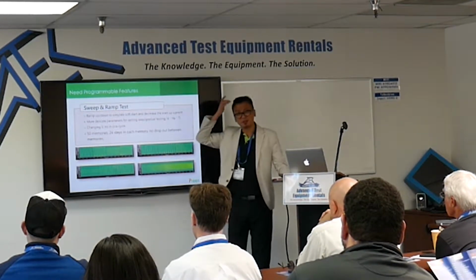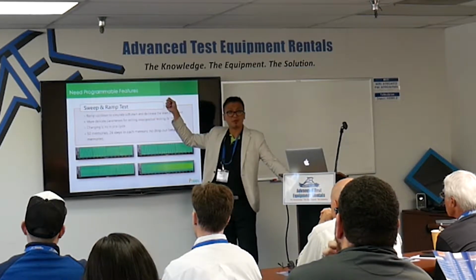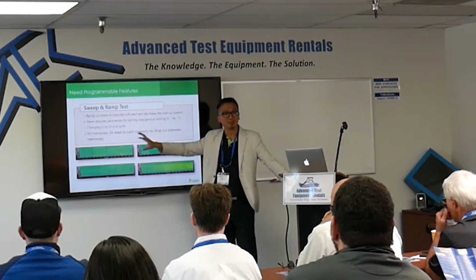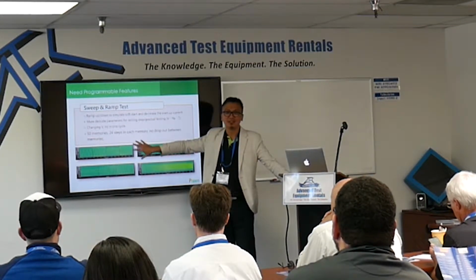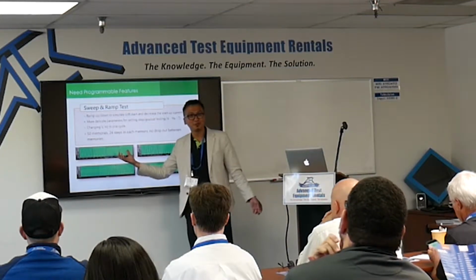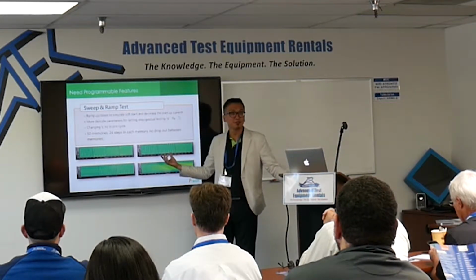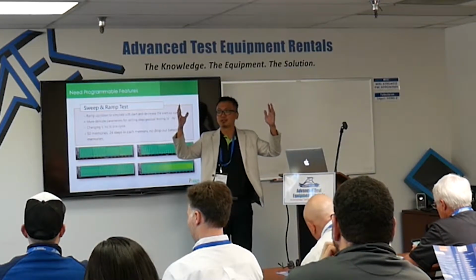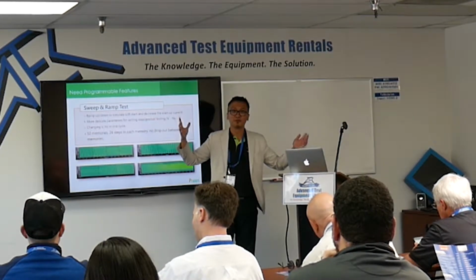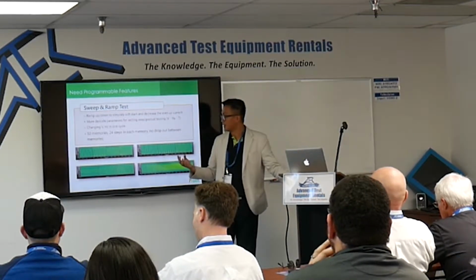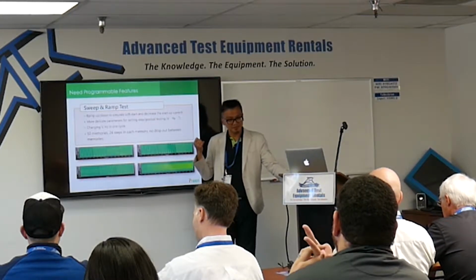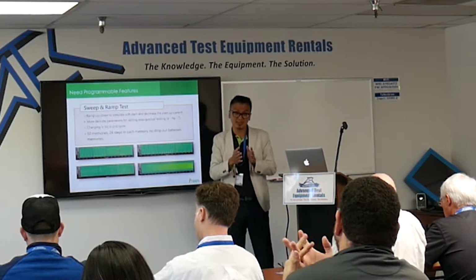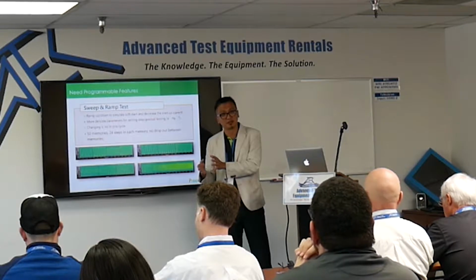Why do I bring this up? Because you will only see the programmable feature in the testing world. In the power conversion world, there's no such feature. They don't need it, because you don't change the voltage all the time. You don't change the frequency all the time. Nobody does that. In a radar system, it's 400 hertz, 400 hertz. You don't have to test at 350 or 450 hertz. You don't do that. That's why some power supply manufacturers only make testing power supplies. They don't make power conversion power supplies.